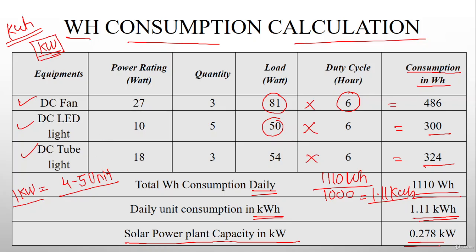But on average, whenever we do the calculation, at that time we take that 1 kilowatt of the solar power plant produces 4 units of electricity on average on a yearly basis. So daily 4 units are generated that we are consuming. In some cases higher units might be generated in the winter or summer season, and in the rainy or snow falling season there might be fewer than 4 units generated. But on average, the thumb rule is utilized worldwide whenever we do the calculations.